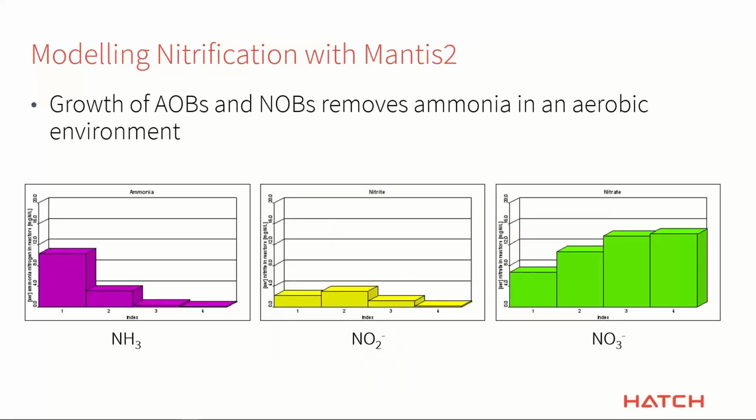And you can see, as a result of running that simulation, I've actually gone in and plotted a bar graph of each of these different species as we look at how this thing does its nitrification. So now it goes downstream as you go from left to right. So the ammonia coming in, this is a plant where the ammonia coming into the facility is at 25 milligrams per liter. That's our default value. So here it's showing that it's about 10 or so, and then down to about 3 or 4, and then fully nitrifying.